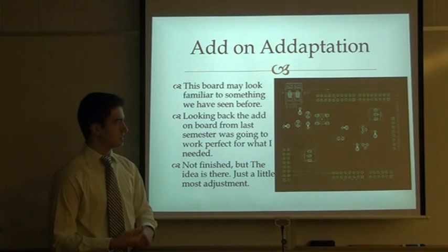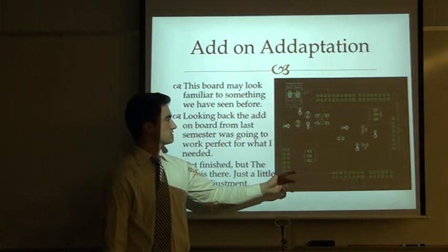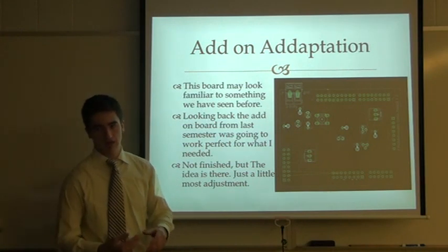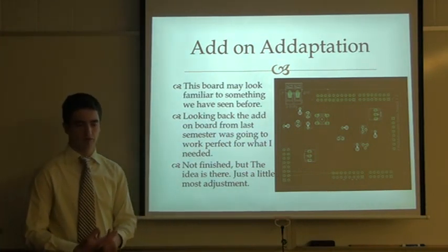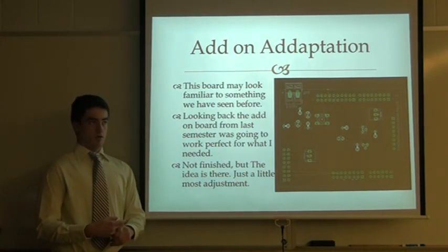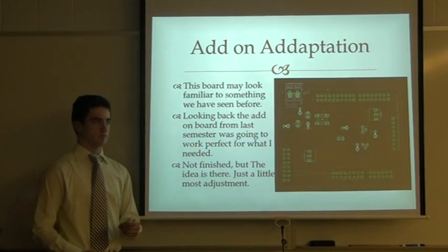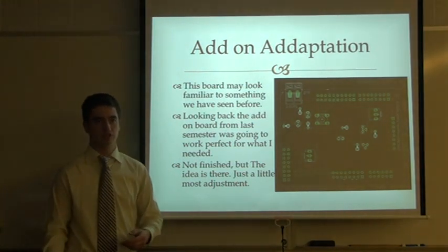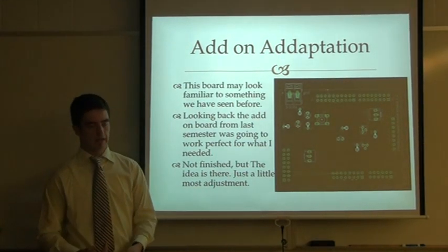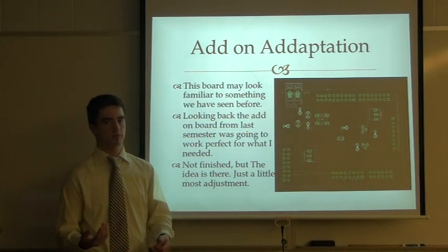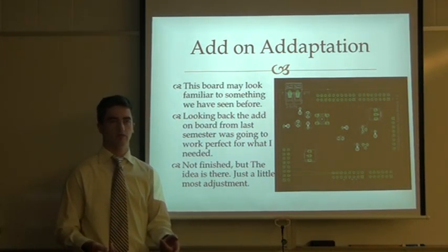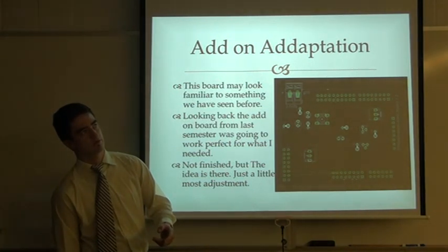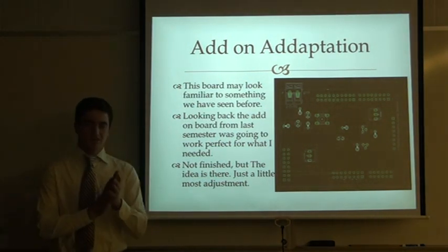So basically, it's got the transmitter circuit already in it. When I was going through the initial circuitry of it, I found a receiver circuit that was already in there, but it was for a photo receiver, not an optic one. It was a similar principle, but I needed a little bit of adaptation as well, so that it would fit. Instead of being a 2-pin photodiode, it's actually a 3-pin photodiode transistor combination.